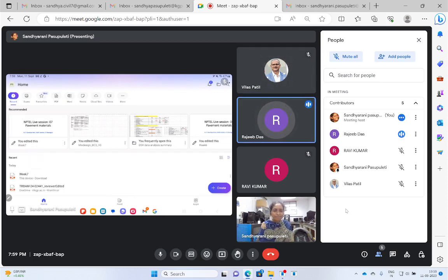Is there any property difference between the tack coat and prime coat? Both can be the same material, but the prime coat should have lesser viscosity than the tack coat because we want the prime coat to percolate more into the granular layers. So the tack coat can be a little bit viscous, but the prime coat should always be very less viscous so that it can serve the purpose.